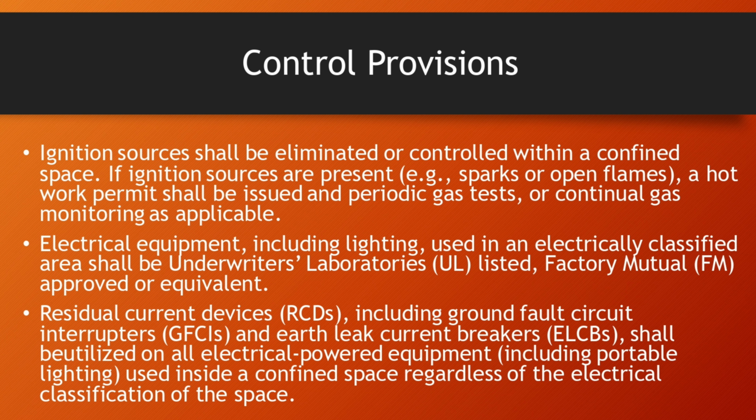Electrical equipment, including lighting, used in an electrically classified area shall be Underwriters Laboratories, UL, listed, Factory Mutual, FM, approved, or equivalent.